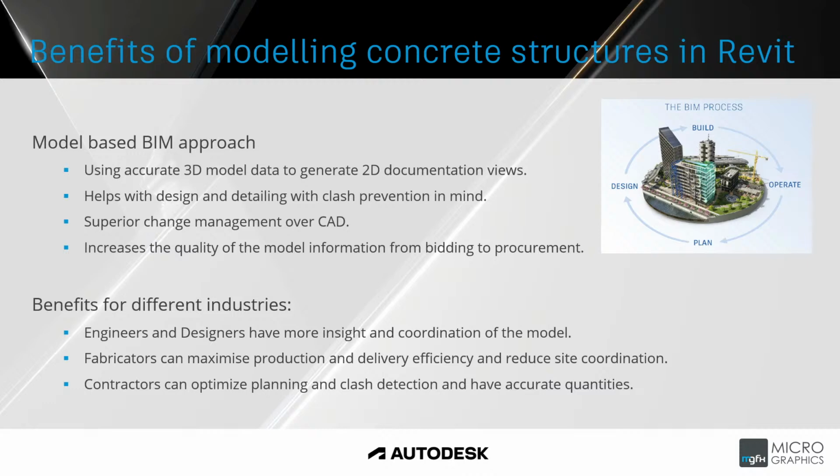Fabricators can be more efficient because they've got more information within that BIM model, and they can reduce rework and coordination on site, so they can plan ahead of time and know what they're in for, creating these rebar shapes.